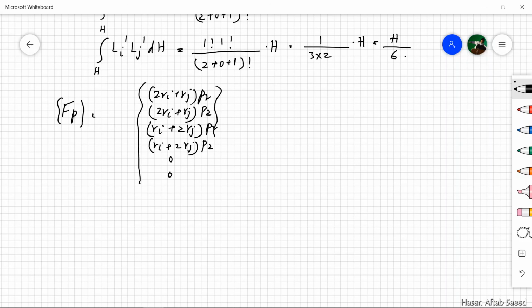On the outside we have pi hij over 3. Now this hij obviously will be replaced by jk or ik depending on which two nodes are relevant to the pressure, and in that case the position of the zeros will also change. The first two points correspond to I node, then the j node and the k node. Here the k node is irrelevant, so we are using zeros here.